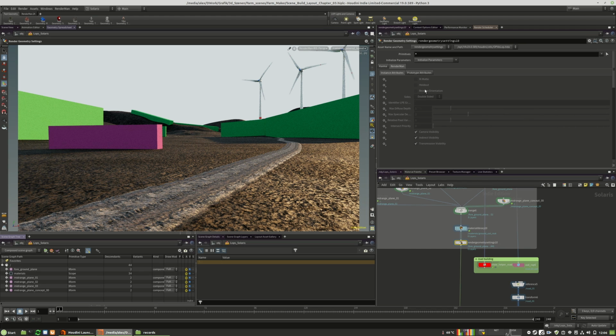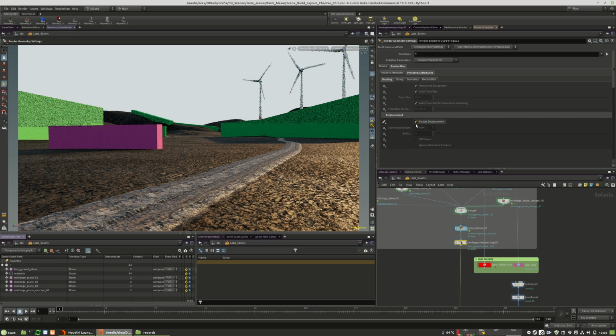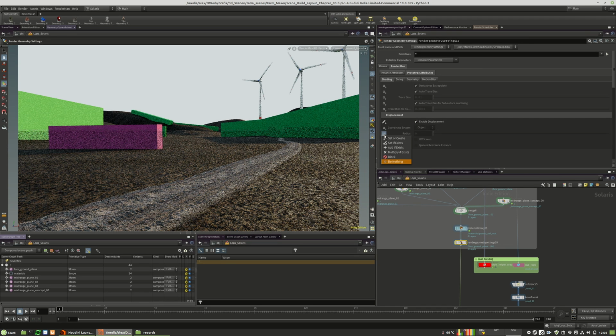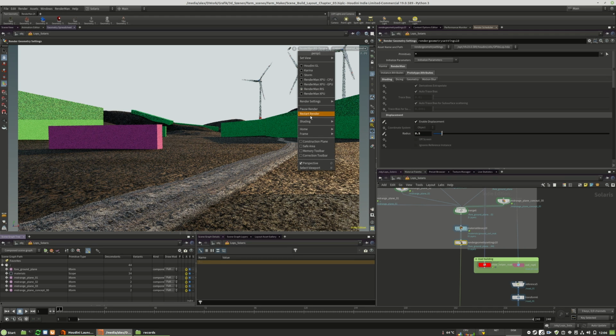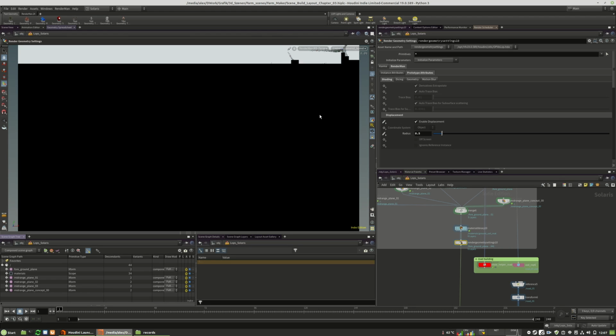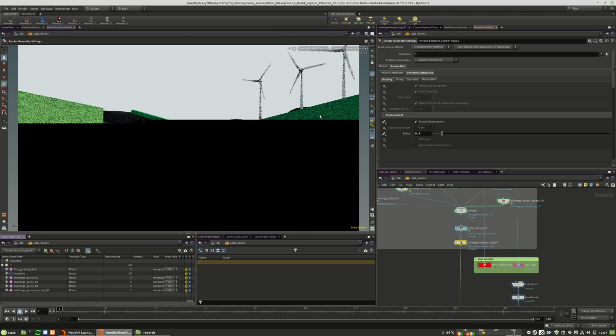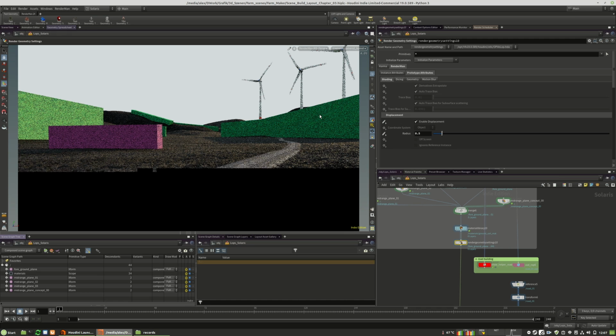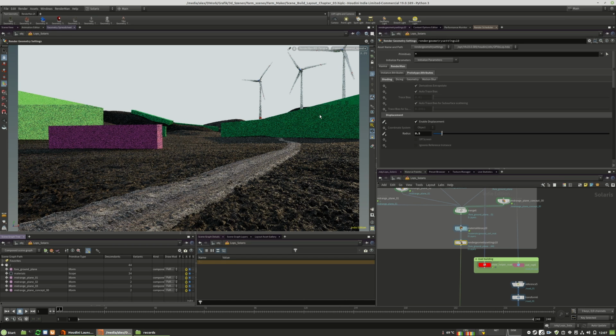We go to the RenderMan tab, to prototype attributes, and here we will set or create the displacements, and here we also need to raise the radius for the displacement. We even could make it something like 0.5, and then we have to restart the render. Now we should get a proper and good looking displacement. And you see it's rendering really fast, and it looks much more realistic, and yeah, it looks really nice.